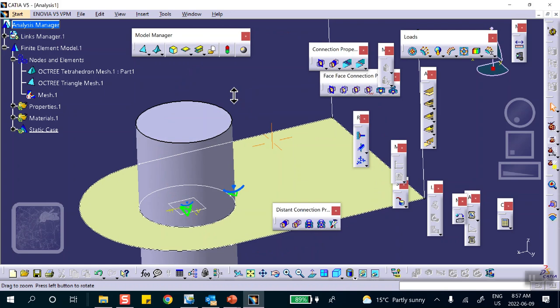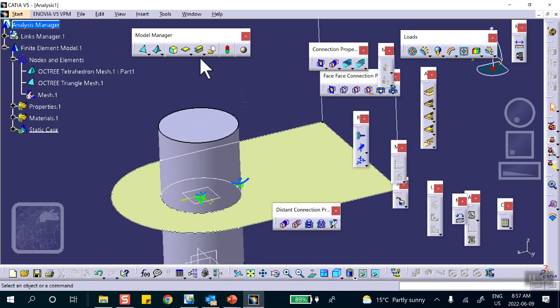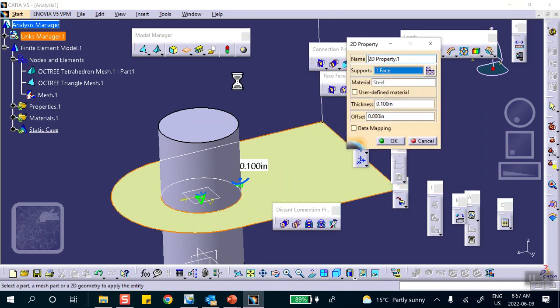Okay. Let's put a thickness on this mesh also. There is the 2D property, thickness. See that? You click on it. You select that. Since all the stuff that I use is my own dimensions that I made up, I might as well make the thickness of the shell also. So imagine this whole thing is 20 inches long. Let's say 0.1. Default 0.1 is about 2 millimeters steel, right? Steel sheet. Okay, why not?